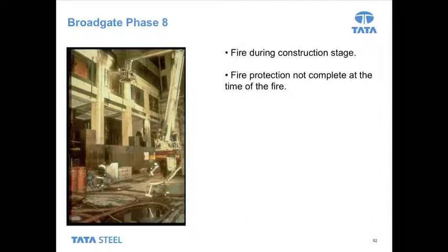So we had a semi-protected steel frame building. Now, everything that we knew at the time about how steel behaved in fires told us that this building should have collapsed for the fire that took place. But it didn't. It actually showed great resilience and it stood up even in quite a serious fire. The other thing that we learned from this experience as well is that the costs of actually repairing the structure weren't as significant as many people thought they might be. And I think it turned out that the structural repair costs were only 5% of the total bill.